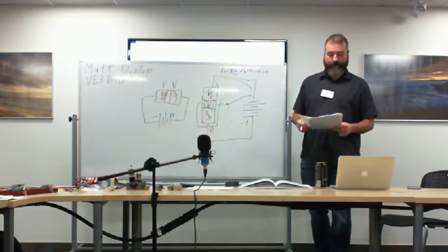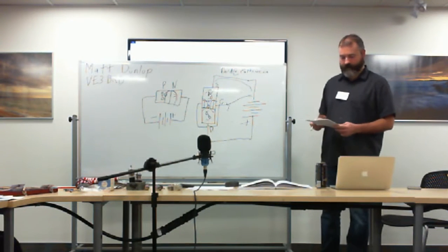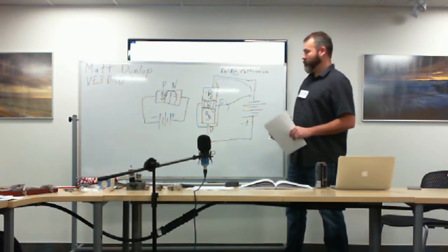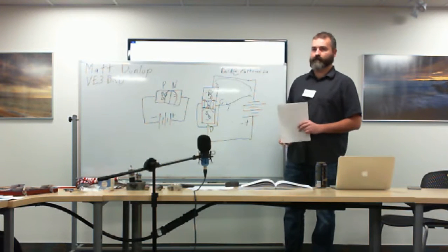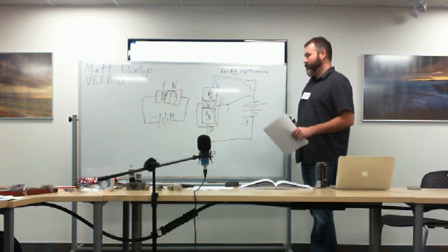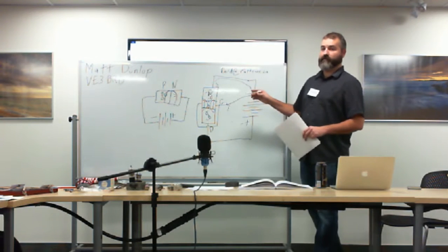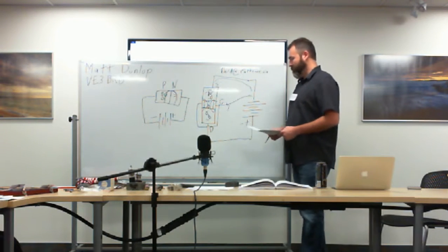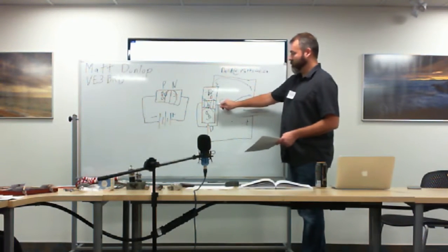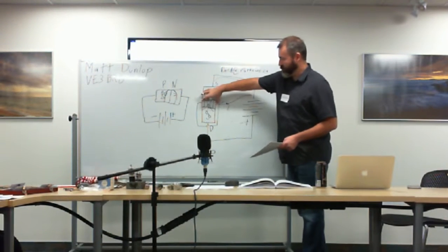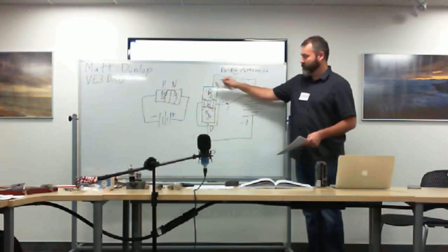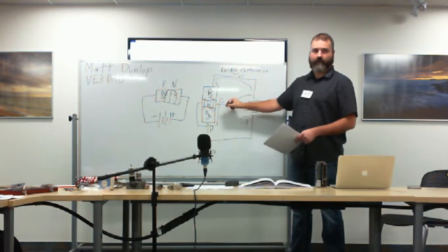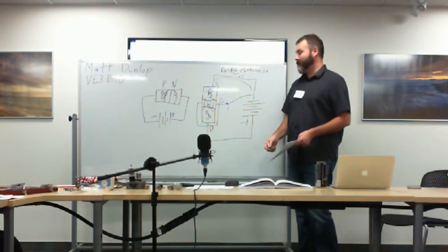So, just so I'm clear. Yep. So one is used to do something after the power gets so big, or it gets so much voltage. The other one is to stop it after the voltage. That's how you can use these as a switch, or you can use them as an amplifier to amplify signals, I'll show you in a little bit. Because this gate here requires a lot less electricity to actually make the depletion zone go across than the amount that's flowing through here. So you can control a large flow of electrons with a relatively small flow of electrons. I guess that's an important thing I should have pointed out.